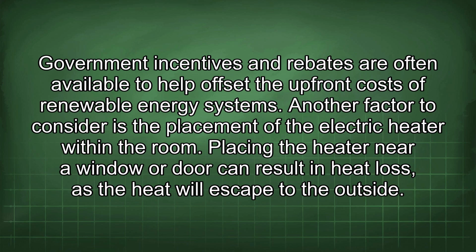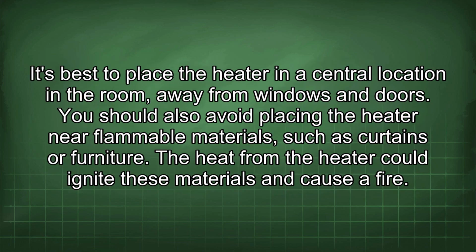Another factor to consider is the placement of the electric heater within the room. Placing the heater near a window or door can result in heat loss, as the heat will escape to the outside. It's best to place the heater in a central location in the room, away from windows and doors. You should also avoid placing the heater near flammable materials, such as curtains or furniture. The heat from the heater could ignite these materials and cause a fire.